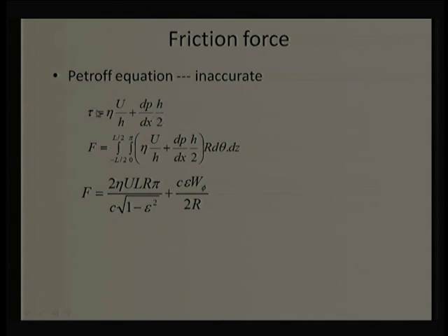To find out friction force, naturally we need to integrate the shearing stress over its area, and that area is r d theta, because of polar coordinates, into dz, the axial length. We have already demonstrated that the effective bearing is only half of the bearing. That is why the integration for theta will be from theta equal to 0 to theta equal to pi. We again mentioned that at the mid plane we are assuming z is equal to 0, so the extremes will be minus L by 2 to plus L by 2, where L is the bearing length. Once we integrate this, we get this expression.